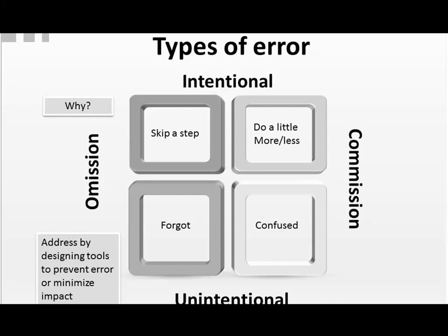But what I'm trying to say is, and let me give you an example, an intentional error of omission. If I want to make sure you don't skip this step, I need to make it very explicit in my procedure, saying, caution, if this step is not performed, this could happen. Now you say, do I have to do that with everything? No, you're going to do that with the ones that are going to create a deviation if they don't, or critical enough that you want to address as a preventive way in the procedure.